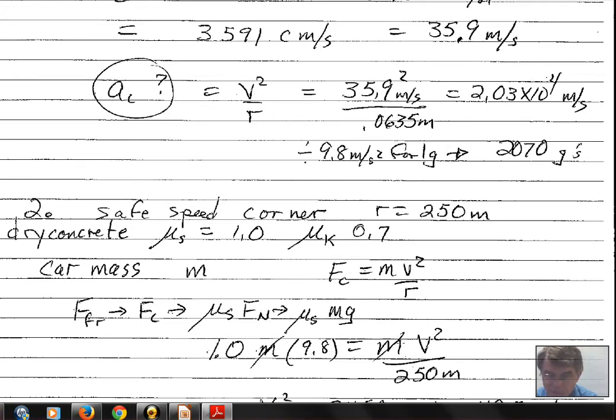This is nice that the universe works this way. So highway engineers can build curves that work for Cadillacs or work for Volkswagens. The mass of the car does not matter. The same posted speed limit for the curve works for both vehicles, assuming they both have coefficient of friction of 1.0 for their tires on the road.